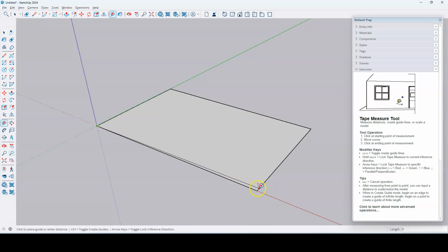And then go ahead and click your other endpoint. If you just hover, that little dialog box comes up and confirms for you that it is indeed the 5 feet, but it also tells you down in your measurement box that you did just measure 5 feet. And then if I click on these endpoints, clicking once, and hover over that endpoint, it tells you 3 feet.